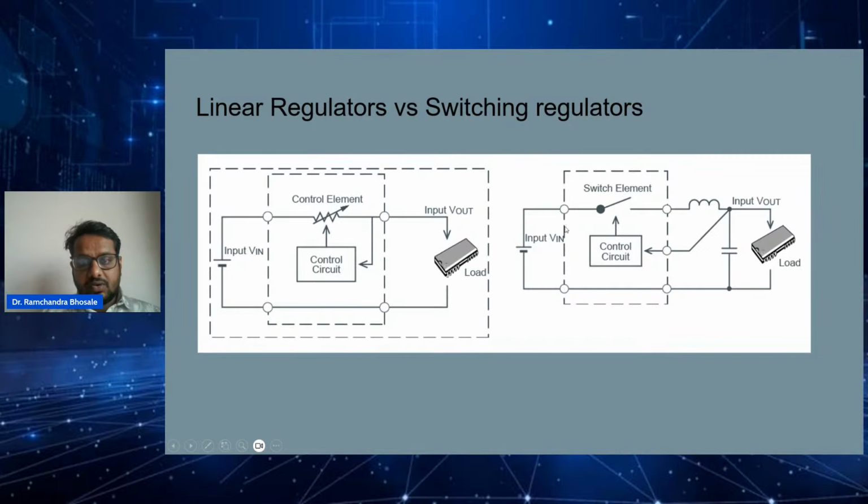But this is not the case with the switching regulator. In a switching regulator, the MOSFET or the IGBT or JFET will be working only in two states, either in saturation state or cutoff state. That means the MOSFET will be either completely on or completely off. So in this case it will not behave like a resistor.